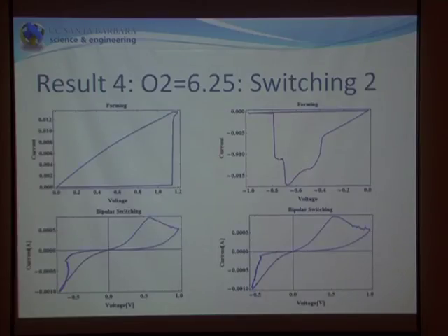And you can do this for a couple other devices. You can do it for different polarities. And as you can see from both of these forming directions, you can still get kind of the same polarity. So I'm not entirely sure what this initial state represents, but I think kind of a better measure of what's going on in the film is the fact that after this relaxation step, your baseline film from which you proceed to do resistive switching is in general a very, very conductive film. And so that's why you see all this behavior at relatively low voltages.